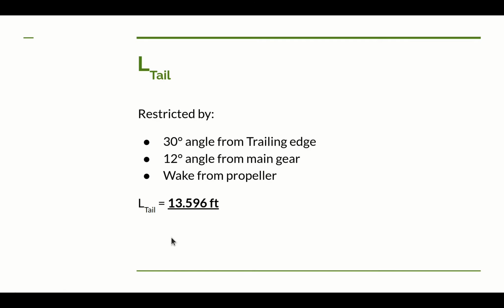So using the measure mechanism in OpenVSP, I did a measurement from the 25% chord of the main wing to the 25% chord of that tail that we came up with, and it is 13.6 feet for that length.